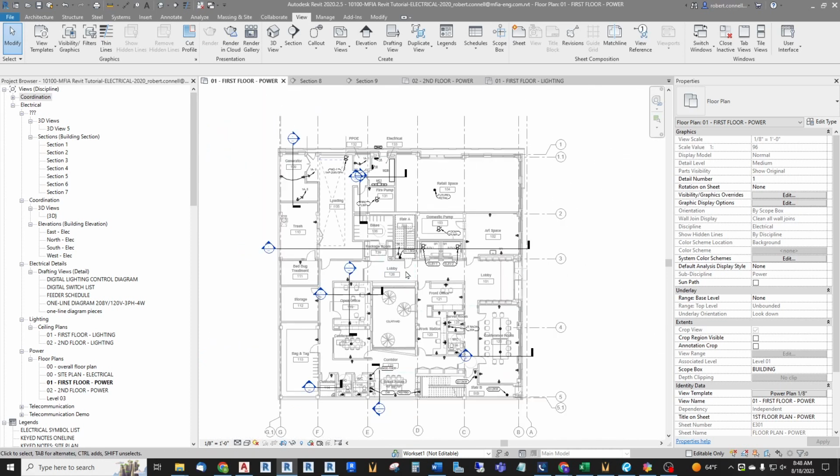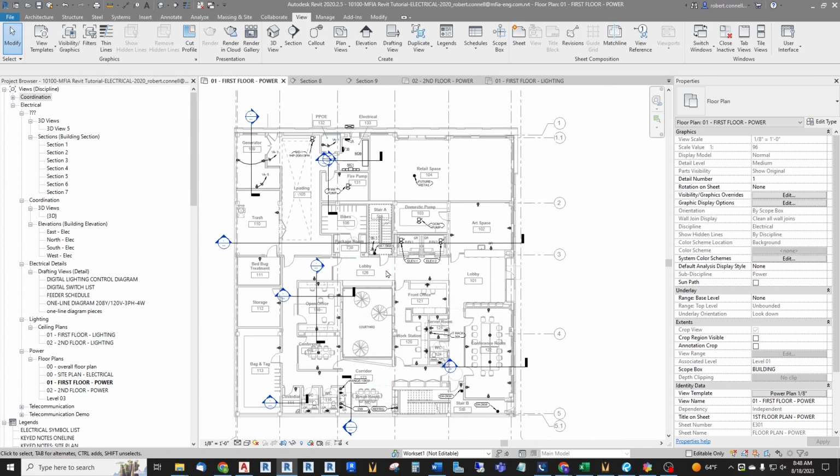Now with Revit, we get the architectural model. We have the choice of what to show on each of our views. So I like to look at view range similar to a section cut. We're all familiar with section cuts. We've used those in CAD forever. So if we look at this floor plan for our sample project, and if we cut a section, you can see this section cut right here through the building.